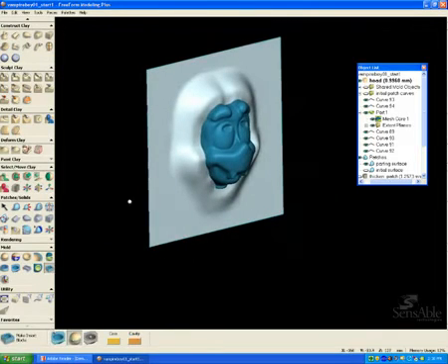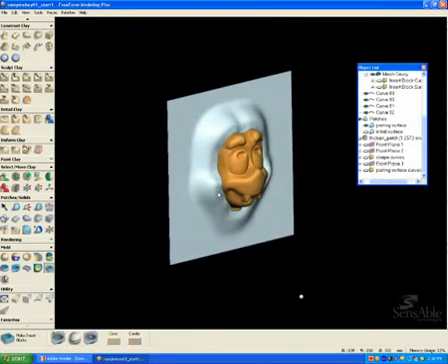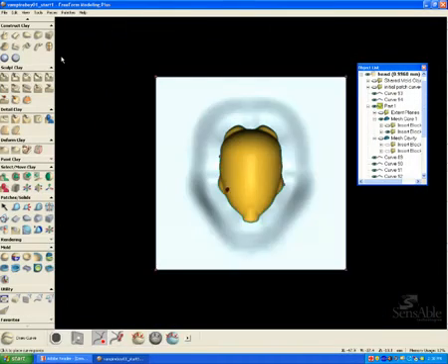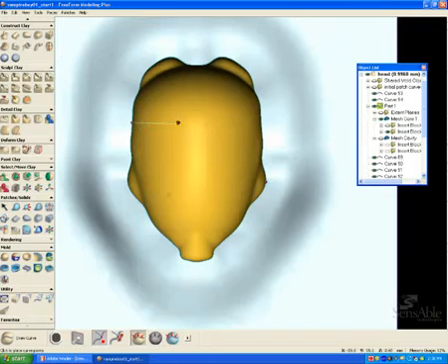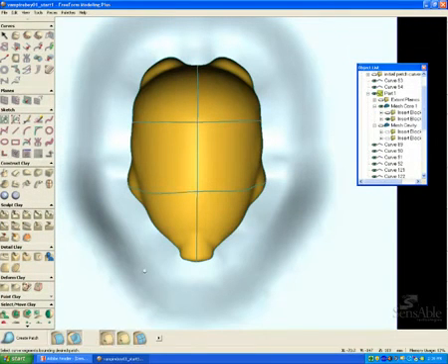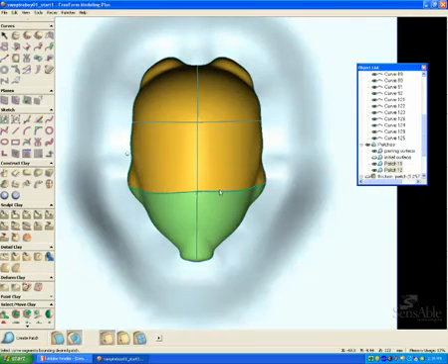I also trimmed the inside where the head is and deleted that piece out because that's where the void is going to be. And now I'm creating these two meshes, one on either side for the two different core cavities. And what I want to do now is draw some curves, making sure that Fit Curve is selected on the Dynabar, and I'm setting up a network where I can start creating some manual patches.